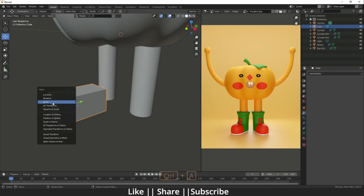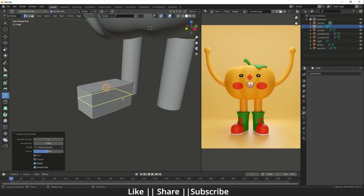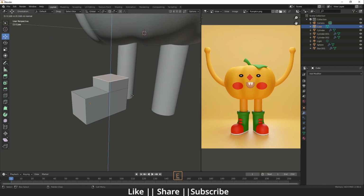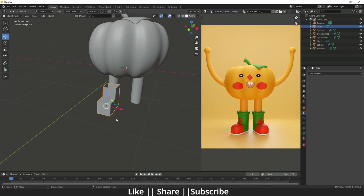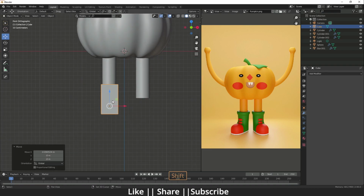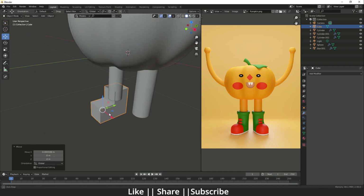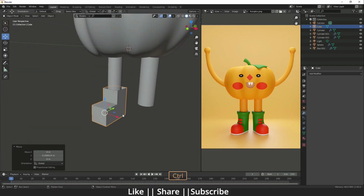And now I'm just going to apply the scale first of all, then I will go to the edit mode of this cube and add one edge loop here in between, and then I will select this upper face and extrude it something like this, and make sure you delete this face basically. And I think we should match this one to this leg, something like this. Yeah, I think that's fine.